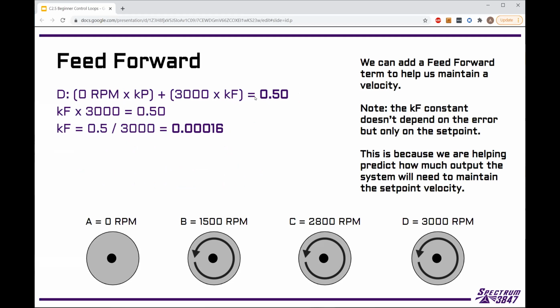The example for this, which we'll try to do, it's a little bit wonky. We can show it doing speed control, but the numbers don't quite work here. The interface doesn't let me put in anything past the 4th decimal, so these aren't going to be exact. And just doing speed control on a motor alone that doesn't have a mass gets a little tricky. It's able to accelerate to a speed very, very quickly because it doesn't have to spin anything up. So you don't really see the curve as well. So I'll try to get a better example in the future.